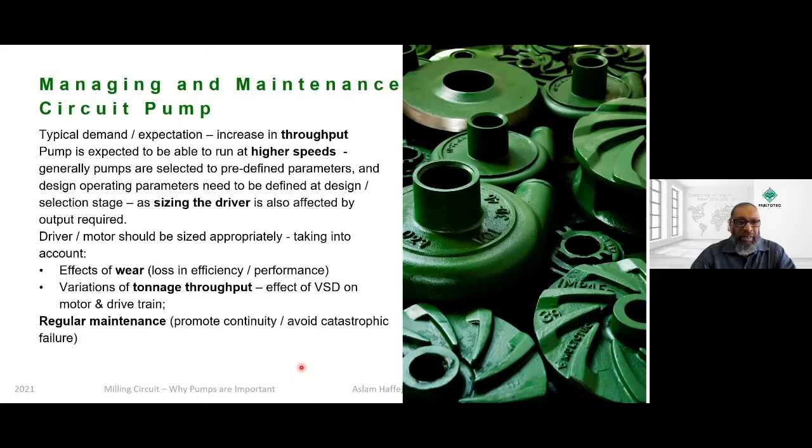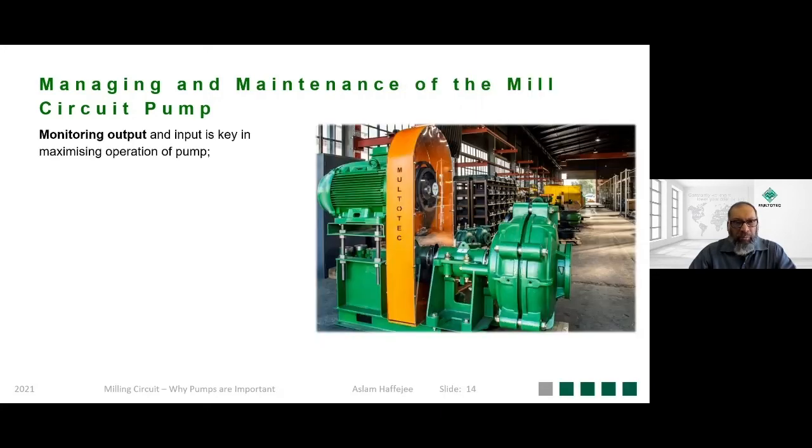So the key here is to promote regular maintenance. You've got to keep your bearing assemblies properly greased or lubricated. It's also important to note that over-greasing is just as bad as under-greasing. The manual lays out the greasing intervals, etc., so that needs to be taken care of. The other thing that needs to be managed is the actual monitoring of the output of the pump.